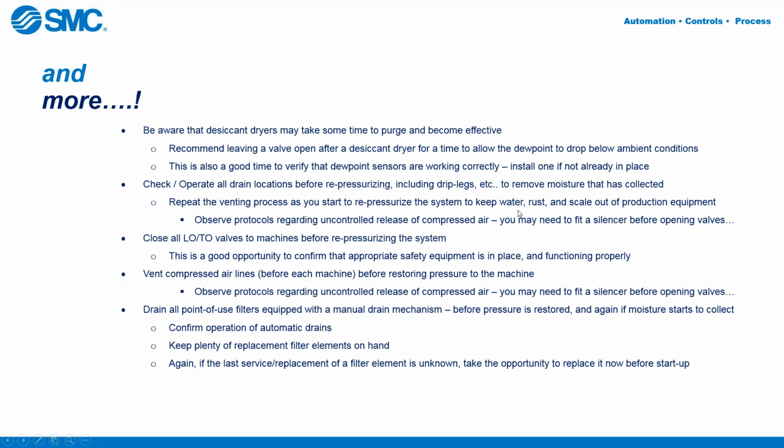You do want to observe your safety protocols. Many facilities have rules against uncontrolled release of compressed air. So before just cracking open a valve on a drain, you may need to fit a silencer or some other device, a coalescing filter or something, to contain that compressed air and any debris or particles that might escape if you just crack open a valve somewhere.